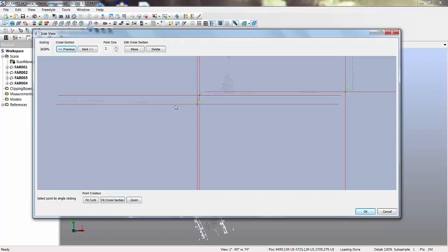The difference between what they're doing and what I'm doing is that, number one, they have the diameter of the survey pole plus the factors of whether or not it was level, whether or not it's been calibrated, whether or not they hit the exact center of the mirror. They have variables included in their position that I don't have.